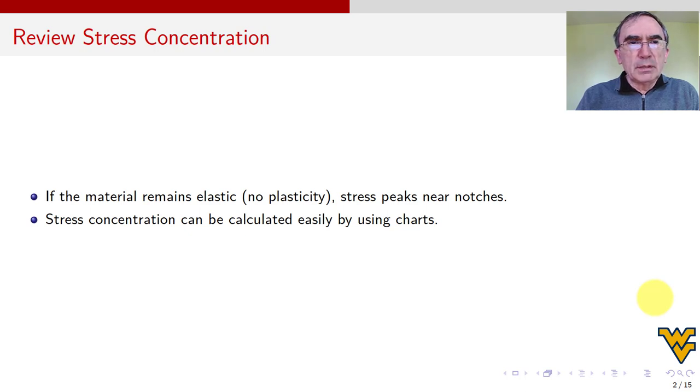Then stress concentration can be calculated easily by using charts, although in video number 1 we used finite element analysis, but that was just to produce pretty color plots. But for this class and for preliminary design and for fast, reliable calculations, we use mechanics of material formulas and a stress concentration factor from charts.